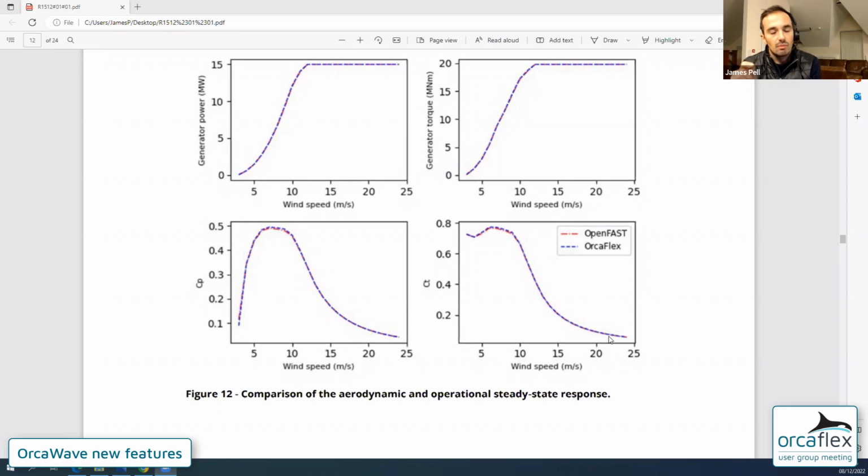But the thing is, the turbine, when the wind speed increases, is still going to go into static stall, and that's going to cause a big drop off in the lift. As such, you'll see a smaller component of the lift in the thrust, in the turbine Z axial direction of rotation. So I think that's what you see, this leveling off.